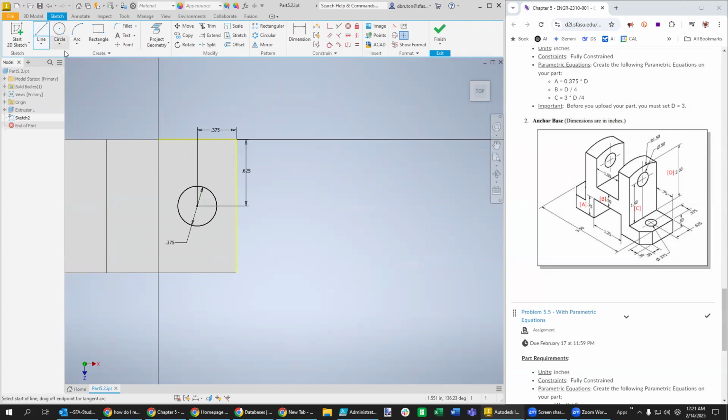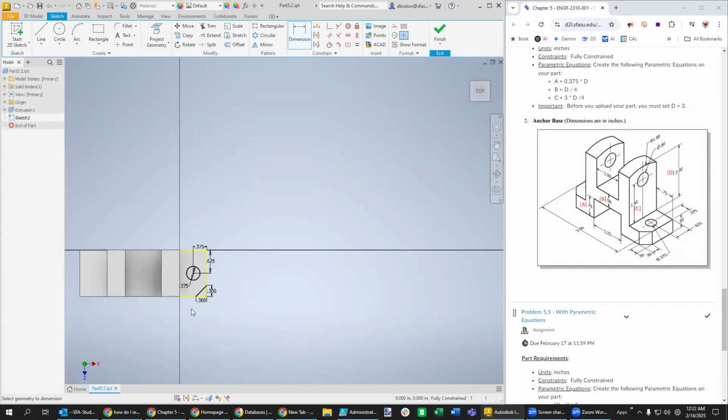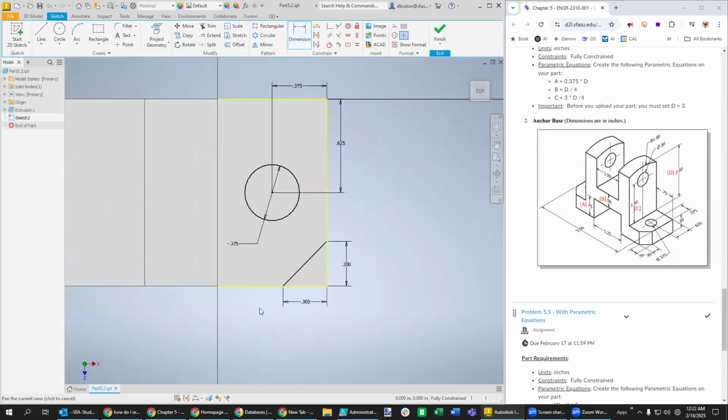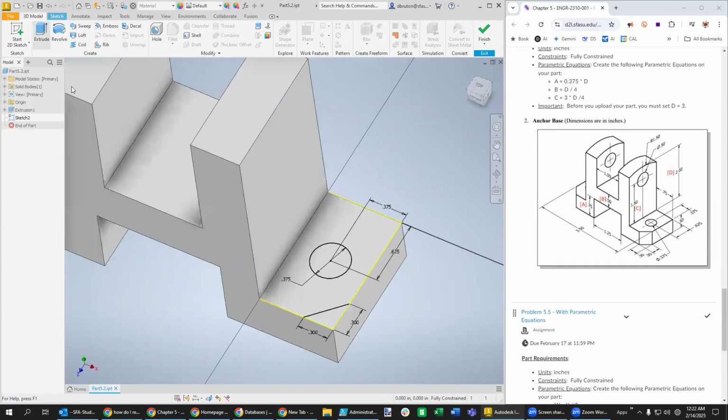And then the next thing we want to do is make a triangle out here. And we want to make sure it's a closed triangle that we can cut through. And we need to make sure that each side is 0.3 units. Now we're finally going to see, is it going to prompt me for the dimensions? And it did. So apparently that reset utility worked. So the lesson learned here is that if you have a behavior happening within Inventor, just go over to that reset utility tool. I'll try to remember this during class as well, and see if that helps us get back to a more familiar environment and behavior within the application.